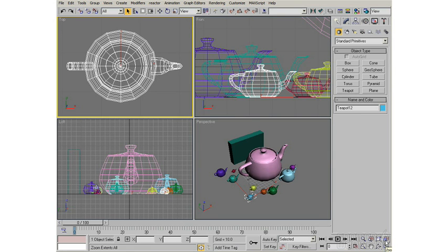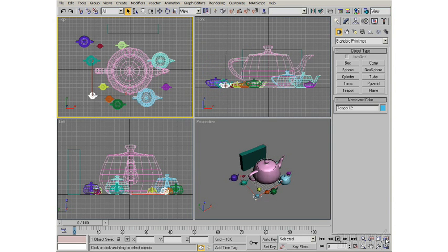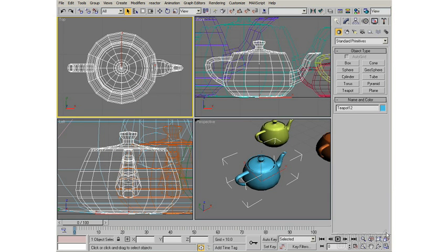Right next to it is a related tool. These tools behave very similarly, but instead of doing it to just a selected view, they do it to all views. So if I click on this, it's going to Zoom Extents in all 4 of my viewports. And if I zoom to selected, Zoom Extents All Selected is the entire name of that tool. It's a wordy way of saying it zooms in every viewport to what I have picked.